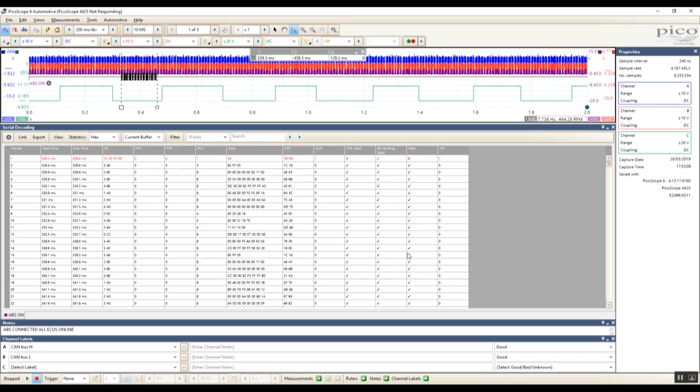And then, of course, the procedure that we've discussed by disconnecting the device, seeing if the ID goes missing, forcing the ID to change the message, change the data fields. For example, pressing the brake pedal forced ID 1AC to change one of the bytes in the data message.